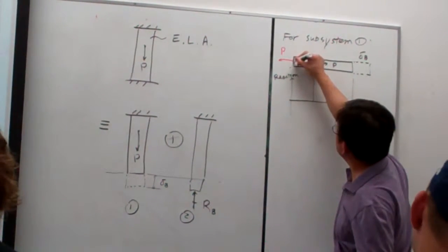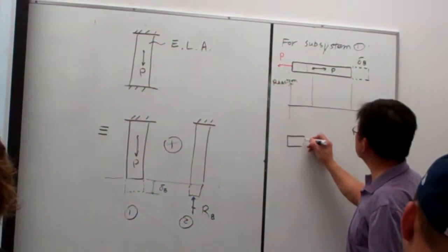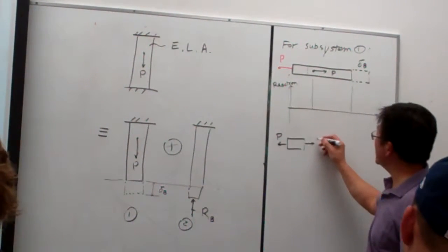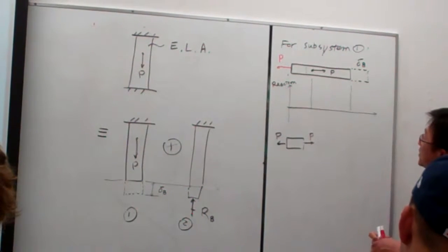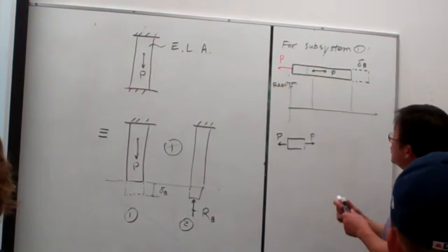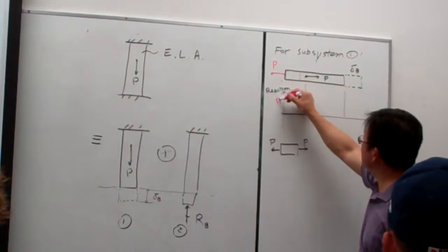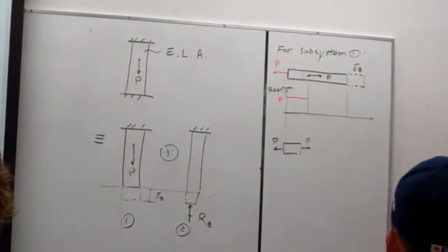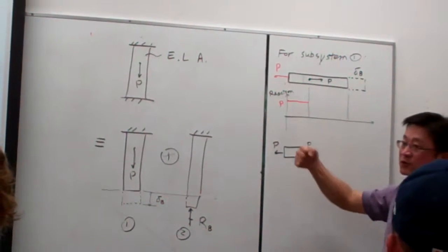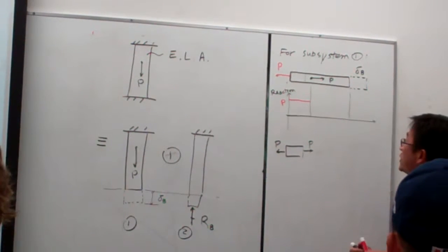Okay, so that is the free body diagram on this part. And then if we take any cross section in this segment, you can see that section has the force P here, and by equilibrium this is force P. So that means in the first segment, the magnitude of the reaction should be equal to P, and that's going to stretch. So that is P here. And again, the point upward is to represent the stretching of the section. The downward is representing compression.